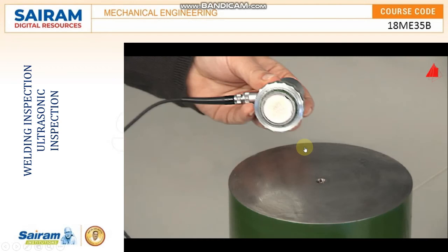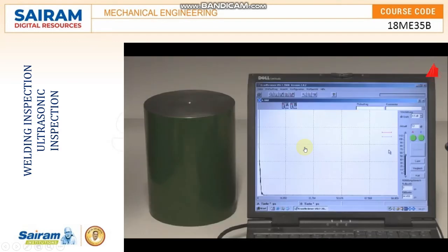This is how a typical probe looks. Under the bright wear plate, a piezoelectric disc is installed. It can transmit and receive ultrasonic pulses. A computer operates the probe via a plug-in card and power electronics. On the monitor, the intensity is plotted upwards and the time is plotted to the right.